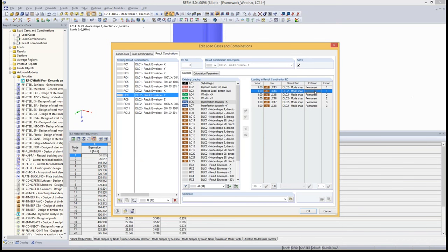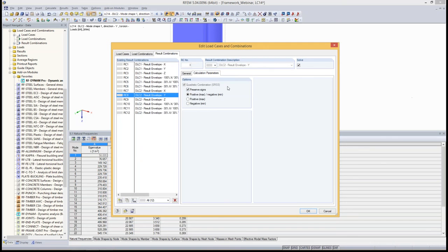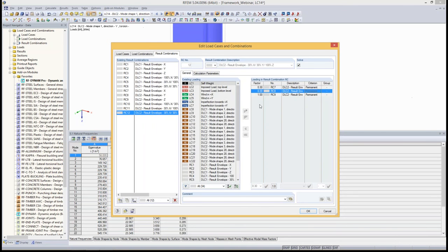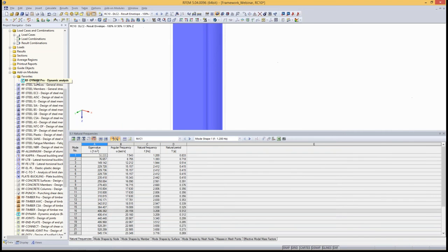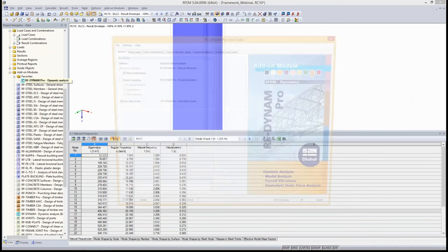The plus torsion and minus torsion load cases are in one group, which means they are combined with an OR combination first, and then the SRSS rule is applied as we explained earlier. The second step is just the same, using the factors 1 and 0.3, as we discussed earlier. So this is what happens with the accidental torsion.